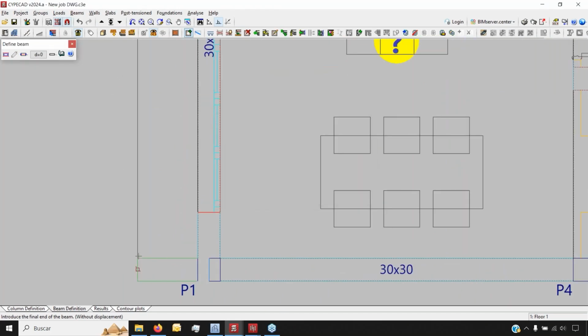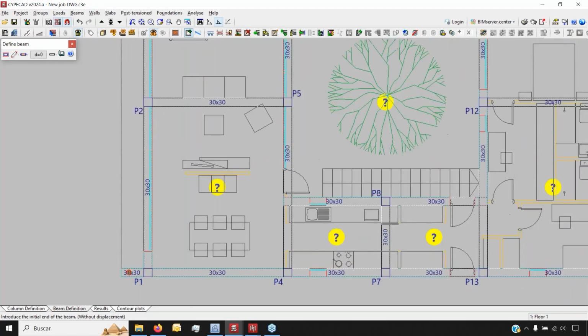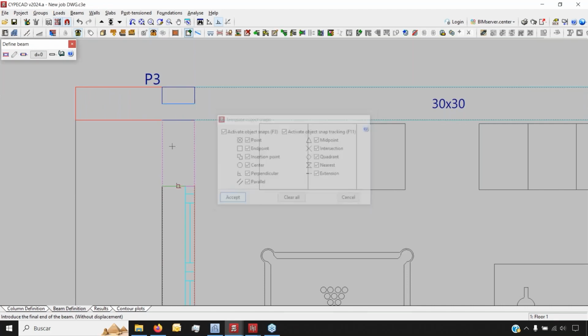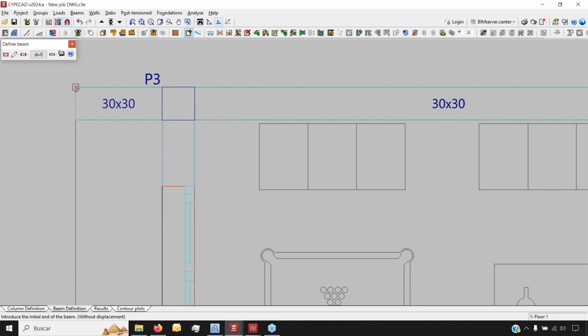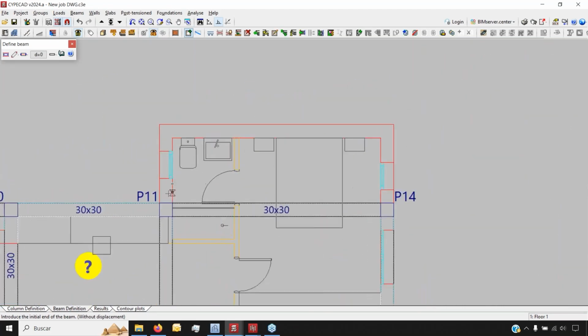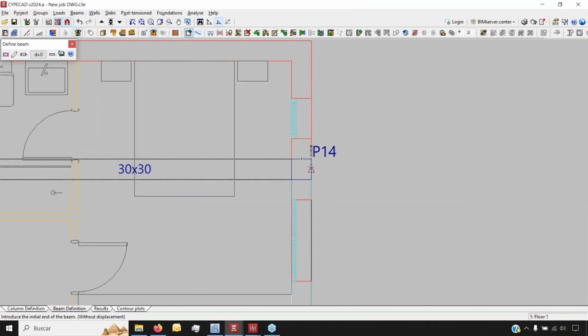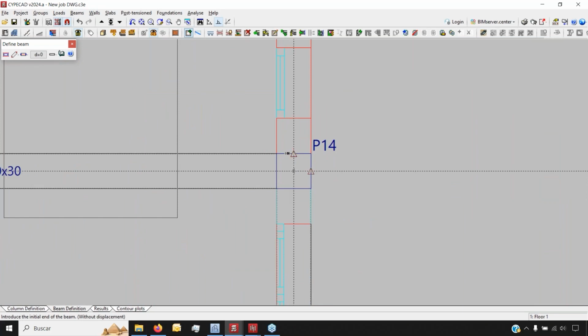Correct. And you can see that if I needed to have overhangs like these ones, I can use my template as a basis to snap to it. So in this case, I'm going to add a few more beams, and once I'm done, I will continue with the panel manager so that we can start with our slabs, of course.